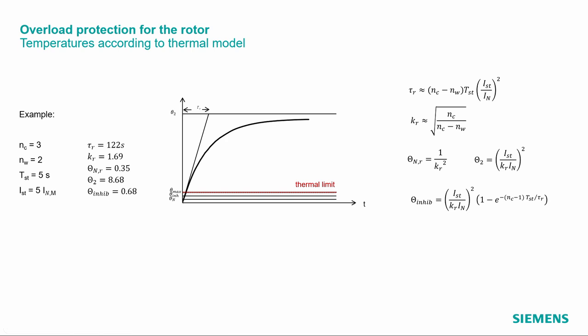I will get roughly 1/3 of the maximum temperature. Therefore, after 1 start, I reach the warm state, because the difference here is 1. So I will land here somewhere at 33%. Now this is not 100% linear, so it's a little bit more at the beginning, and the last step is a little bit smaller than 1/3. So this is how to justify or explain this value.